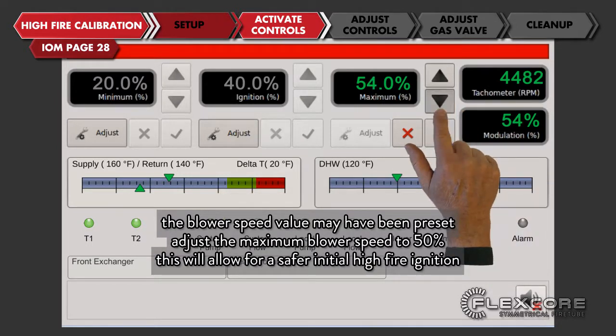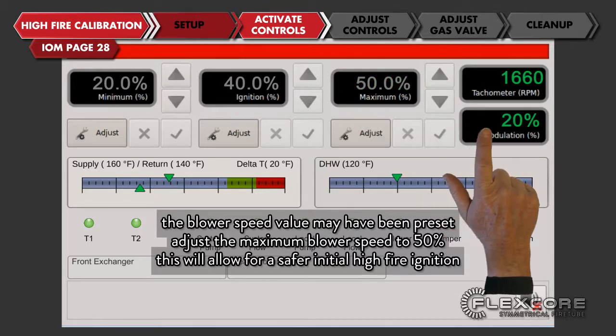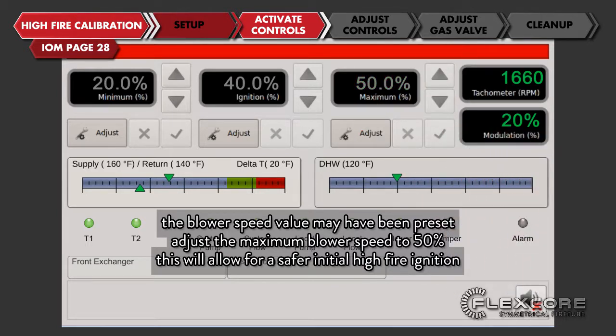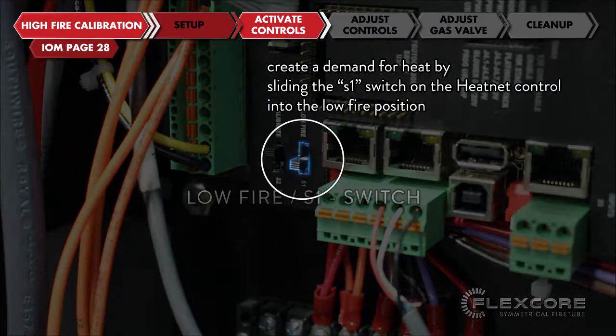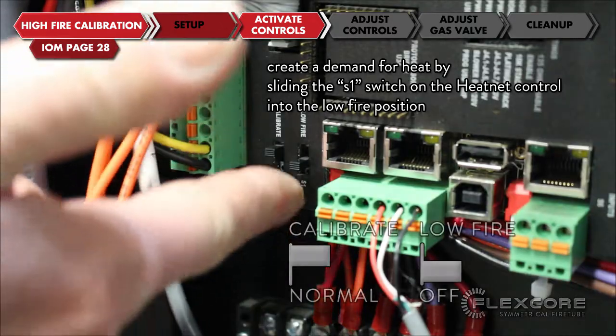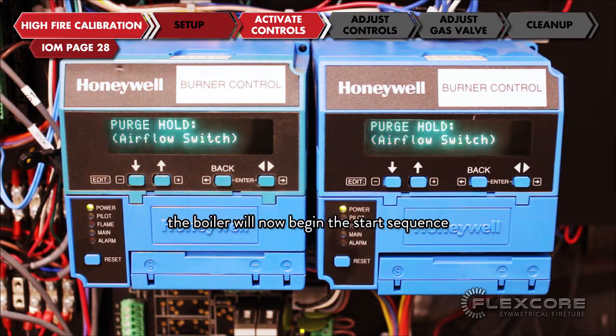The blower speed value may have been preset. Adjust the maximum blower speed to 50%. This will allow for a safer initial high fire ignition. Create a demand for heat by sliding the S1 switch on the heat net control into the low fire position. The boiler will now begin the start sequence.